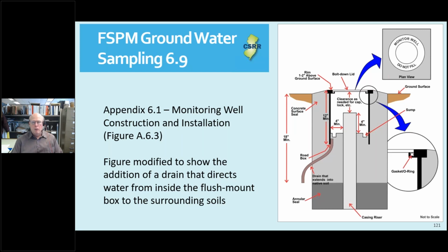Conversely, since the low flow, grab, and passive methods generate a sample that may represent a much smaller zone of the aquifer, it is recommended that a well be vertically profiled before a sampling method other than the volume averaged method is performed. There is an underlying theme in the material that I presented, and that is documentation.